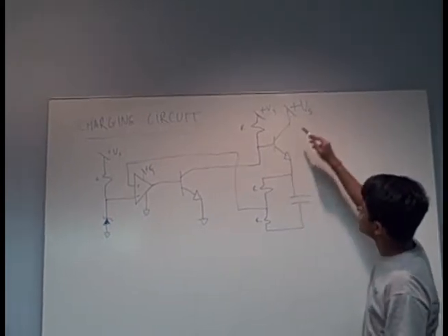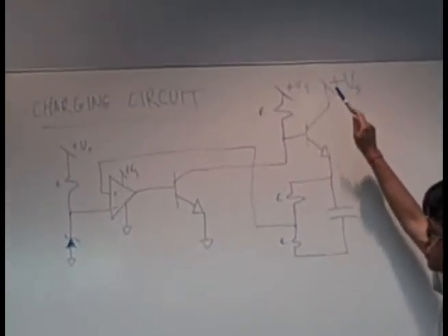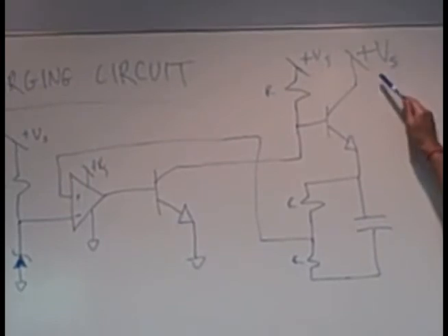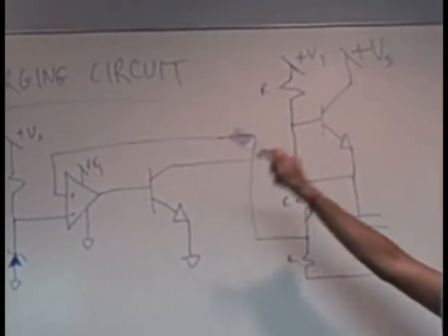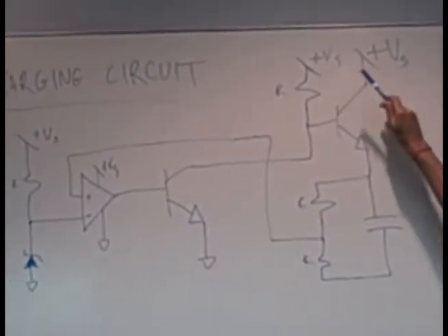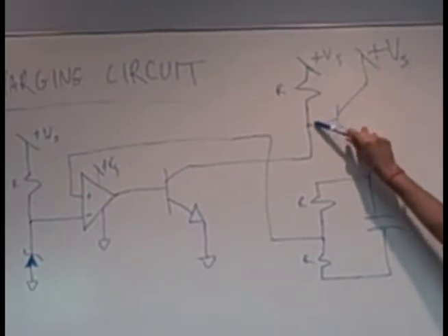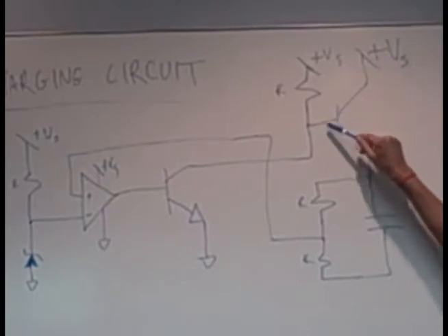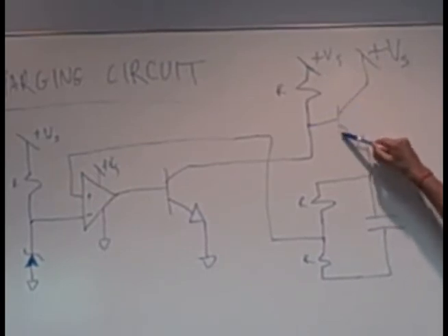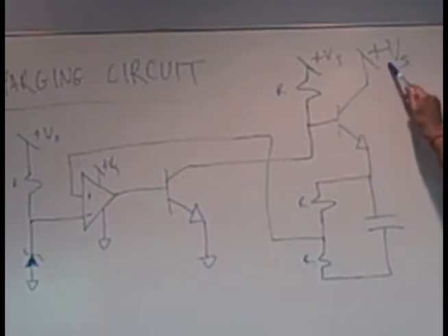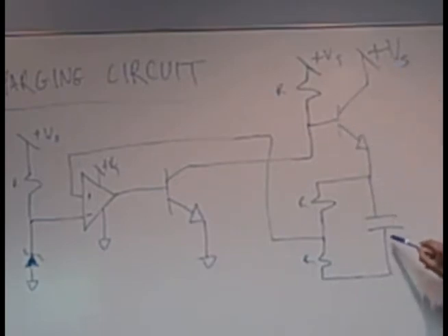Now, as you can see, we first start off with the solar panel. The solar panel, by the way, is represented by our plus VS's throughout the circuit. First we have power from the solar panel coming in, which feeds this voltage to this transistor, which turns it on, which then allows voltage to come through and start charging our capacitor. So it slowly starts charging from 0.